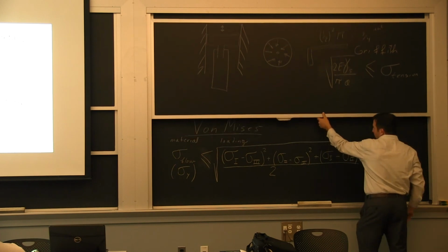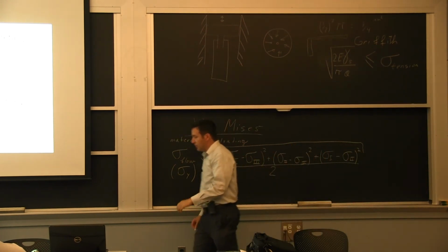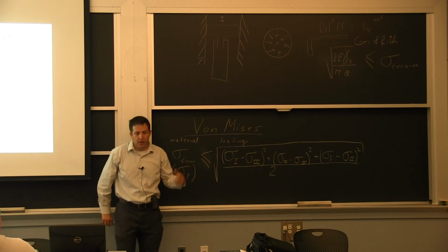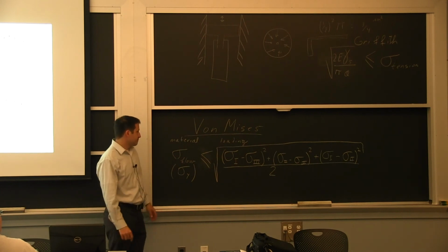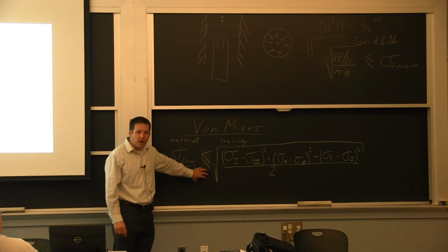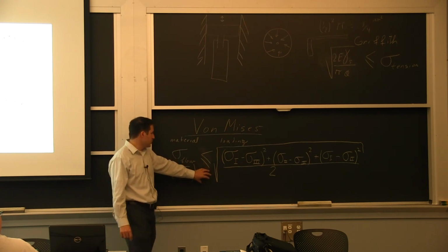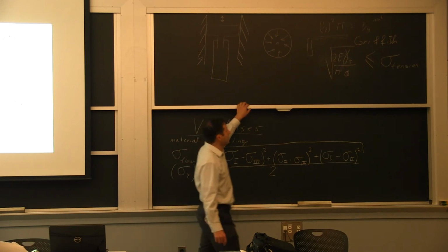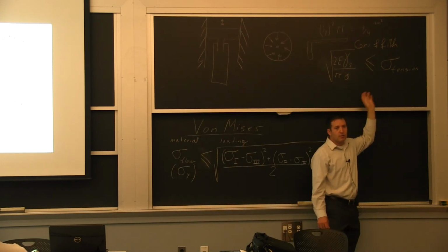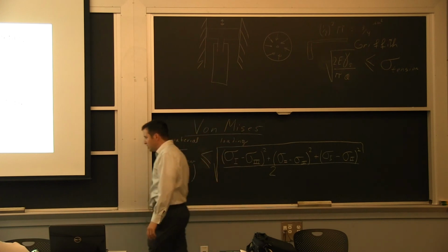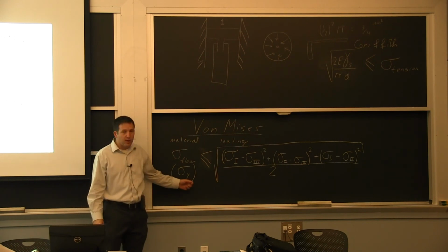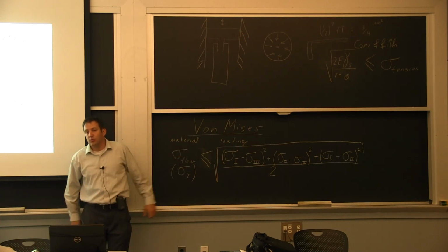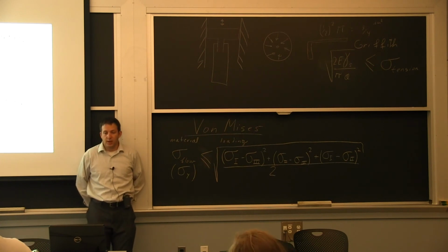So whenever we look at any specific application, if we talk about steel and going from a ductile to a brittle transition, lots of times you can have an effect of the environment, the temperature, or the processing condition on this flow stress. And you can also have an effect on these characteristics here. With respect to temperature, I do want to really point out that this is going to vary the most because it requires the movement of dislocations. And the movement of dislocation is thermally activated.